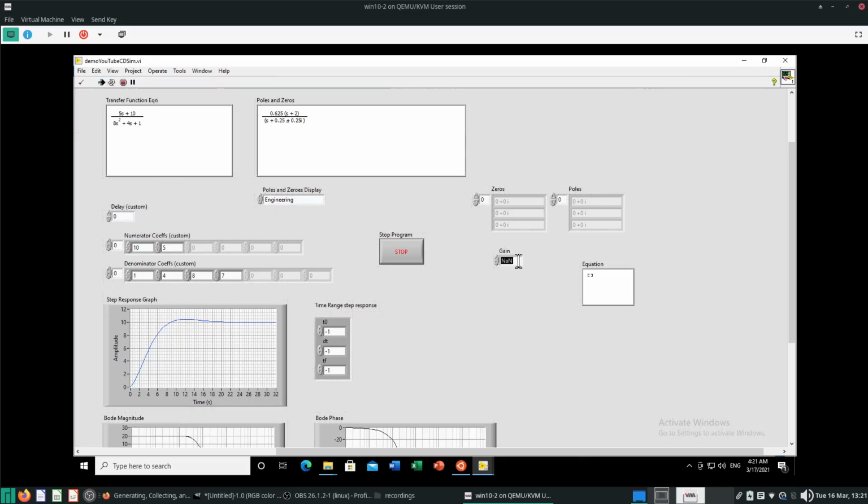Let's say you want a gain of 5, so your transfer function will be just the number 5. Let's give a pole of, maybe, s minus 3, so s plus 3 will be at the bottom. You want a pole of minus 5? Then you will have s squared plus 8s plus 15. So this is your transfer function equation.